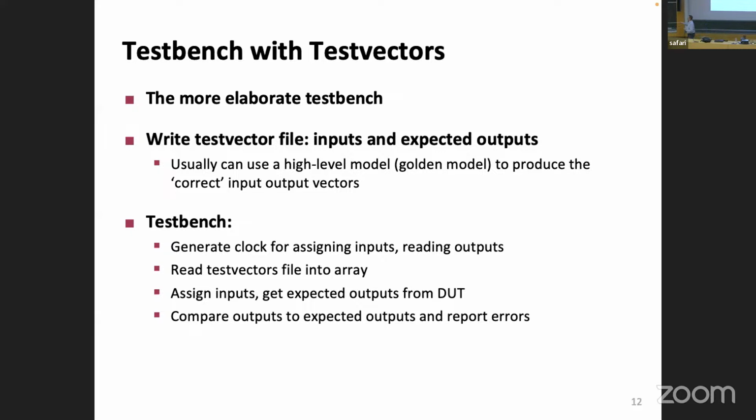It's pretty useless, it's falling, and it's not really helping us do anything because we are specifically only using rising edge triggered flip-flops. And so sometime within this period, in this 1 nanosecond, 10 nanosecond, whatever, let's say this is time 0, and the next one will rise at time 10, somewhere between there, the clock should fall. Okay? It will happen.